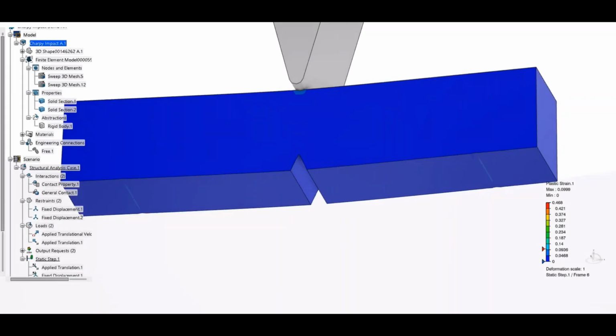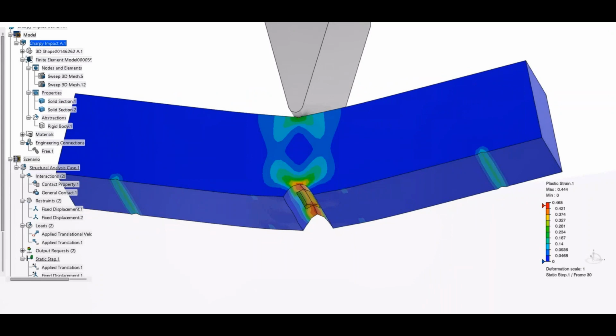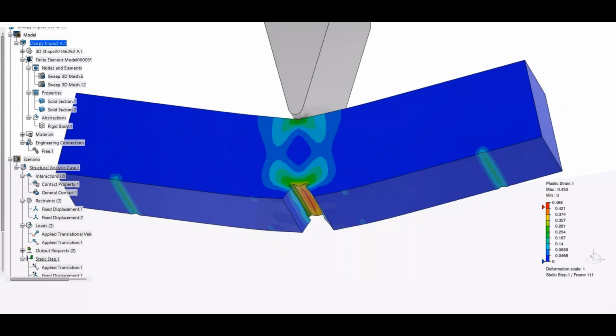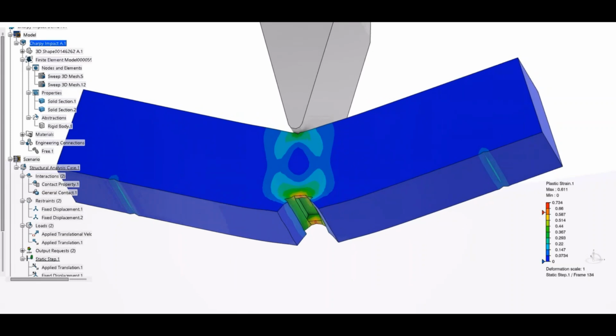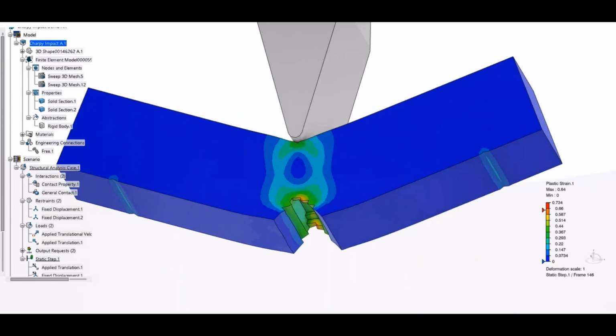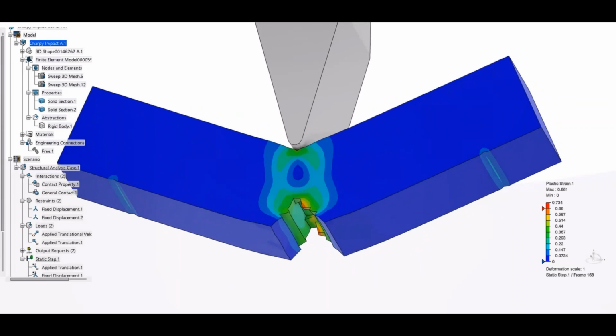And we can analyze it in SIMULIA. So again, here we are applying the ductile damage model. Here in the simulation, you can see in the middle, it's producing the voids. So it's not on pause. The animation is very slow here because there are a lot of small steps, and now the break of the part. So it's producing the break, as we saw in the video.